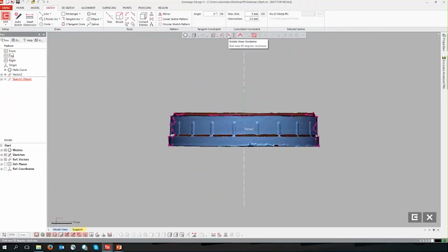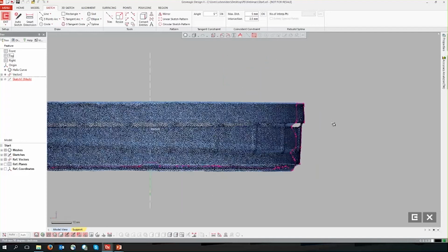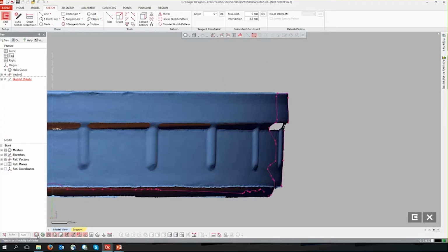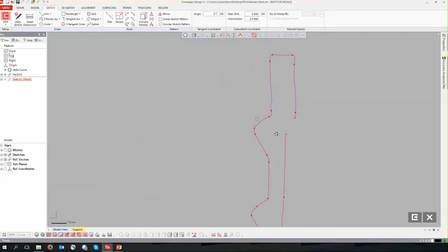And what we're going to do is we're just going to use one of these as our base sketch. So if we zoom in here, we're going to look at this top thread right here. Since, again, this is injection molded, it's not perfect. So we need to start constructing perfect sketch shapes to describe this. So we'll go ahead and just extract the top, and then we'll extract the bottom. And we can kind of see that this is not a perfect triangle.